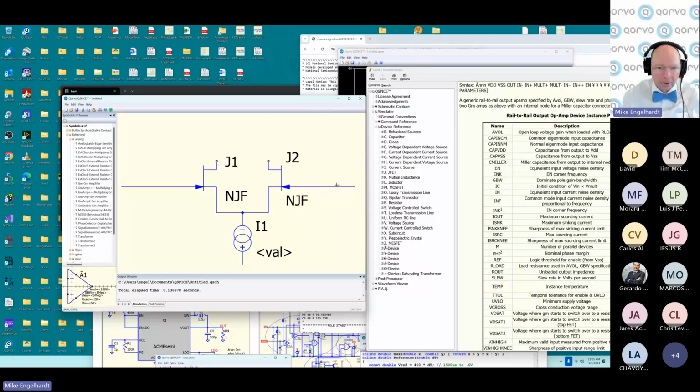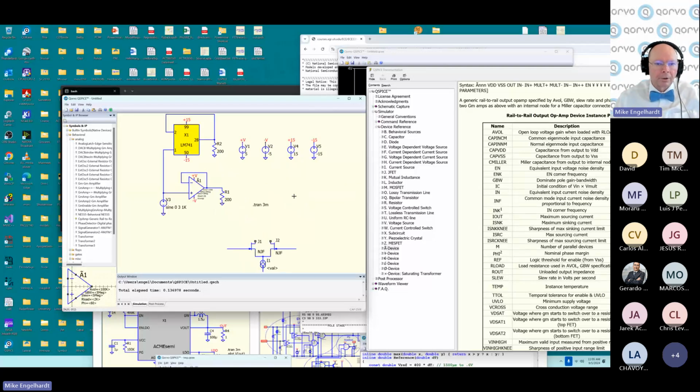which is rejected by the common mode rejection ratio. But the whole point of using op amps is those impedances don't have to be matched. Like here they're not. Okay, that impedance is not that impedance, and so this common mode current will be turned into a normal mode signal, which is amplified by the full gain of the op amp.